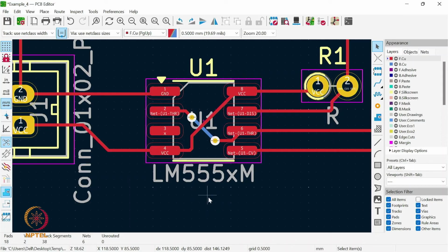First we need to understand the schematic and find out which path is the highest frequency path. We want to route that path on the front copper, and the rest of the slow moving signals we can route through vias. So all this comes through experience when we design PCBs regularly.